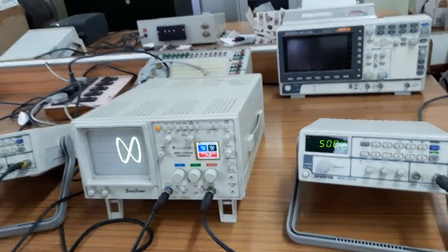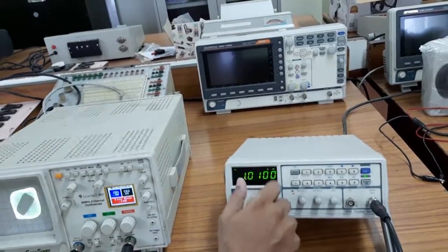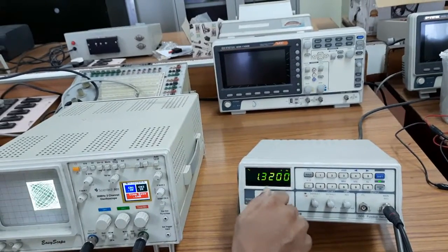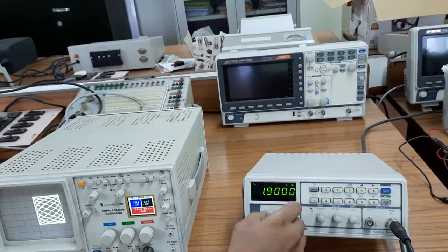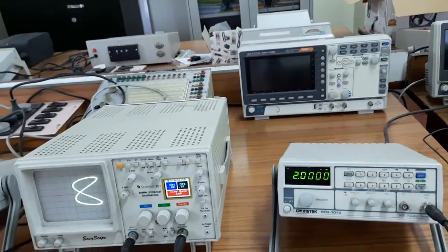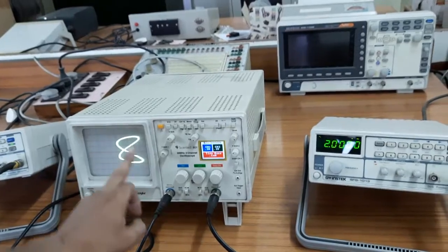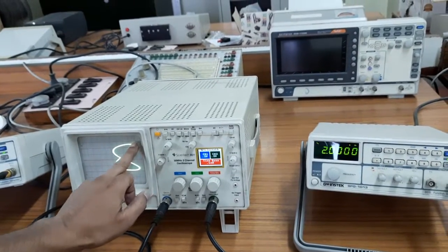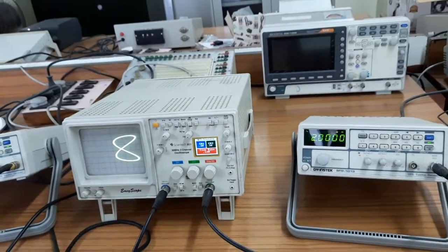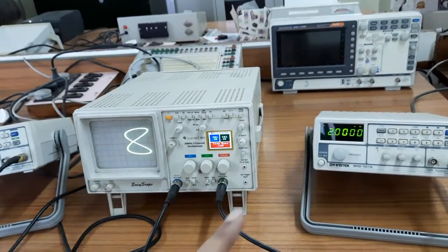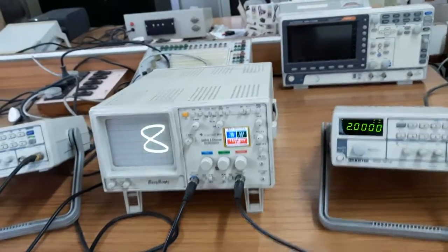Now we are changing our frequency again. Now we try to set it to 2 kilohertz. Now just follow. Here it is 2 kilohertz, here it is 1. So now this frequency is double. Now horizontally only 1 point touches and vertically 2 points. So it is a 1:2 figure. That means this is 1 kilohertz and here it is 2 kilohertz. So any frequency can be measured.